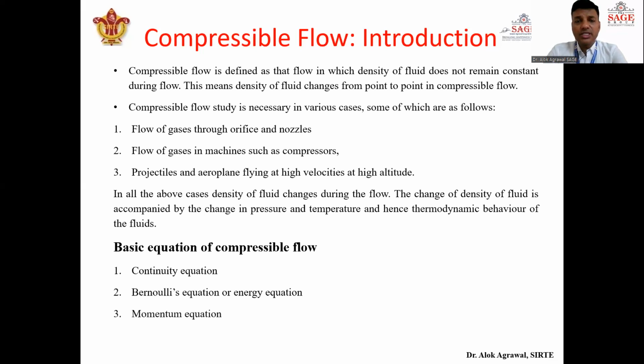There is one more equation, that is the equation of state, PV is equal to mRT, that we have seen in incompressible flow. So for converting that for compressible flow, what do we have to do? We have to take m by V. In PV is equal to mRT, from the left hand side we move that V to the denominator of m, and we can replace it as P is equal to rho RT. That is what we have to do for the equation of state.